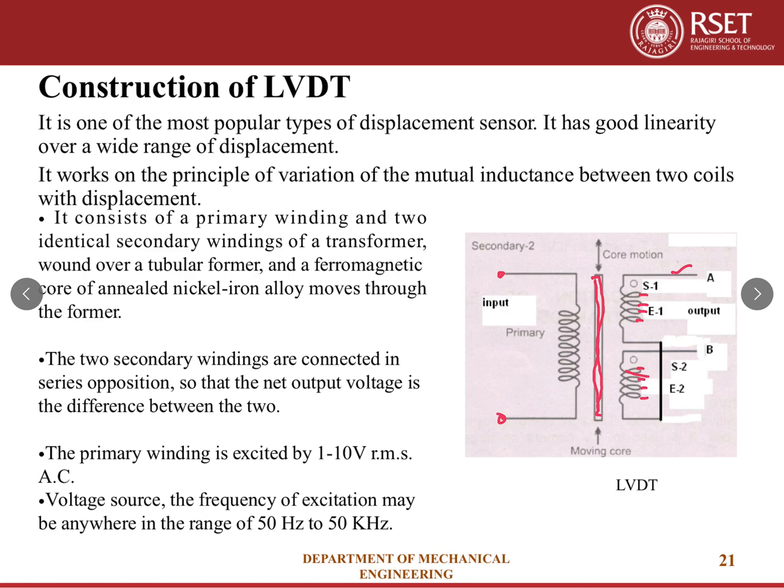So that's the basic construction of LVDT. It is one of the most popular types of displacement sensor. As I said, it has good linearity over a wide range of displacement. It works on the principle of variation of mutual inductance between two coils, S1 and S2, with the displacement.